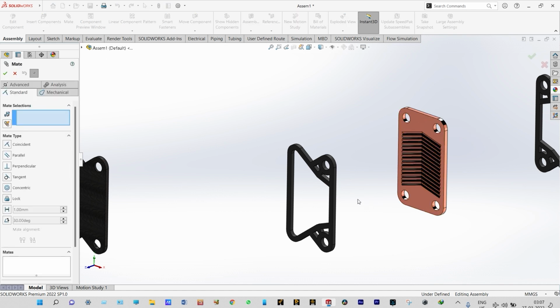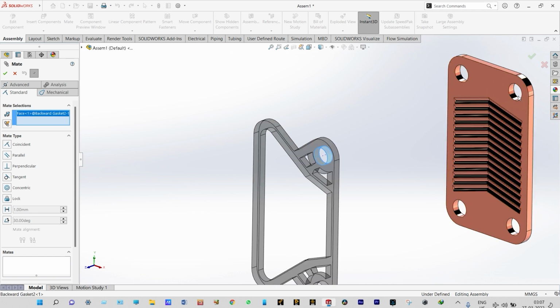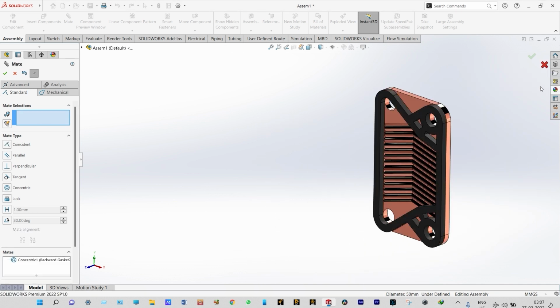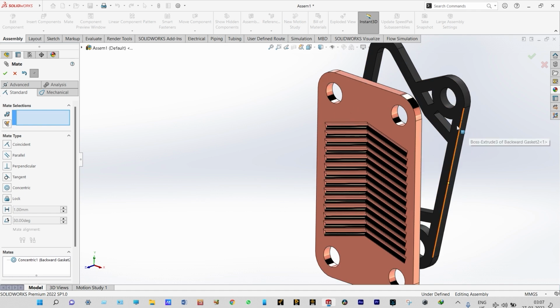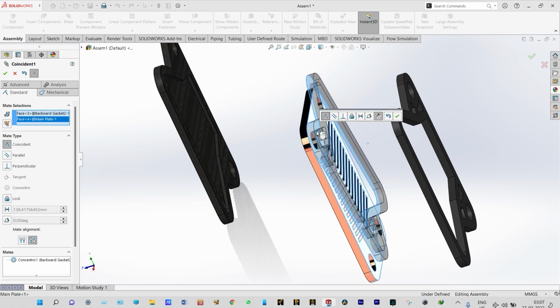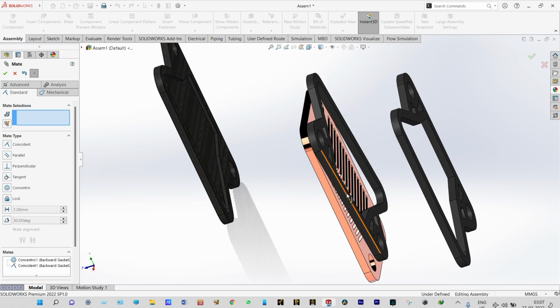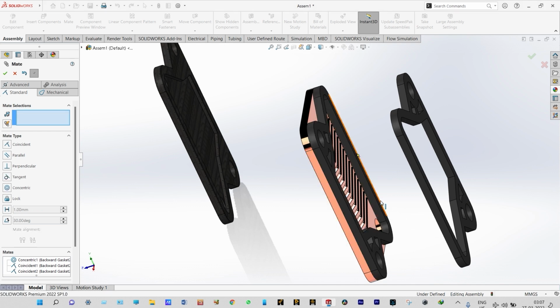So right, and you need to select this one. This hole should be made with this hole. So green check, and this one will be moving back side. So you can select this side should be meeting this side. Two constraints are met, green check, and the third constraint, that is this face and this face should be parallel. Three constraints are met, so one assembly part is complete.